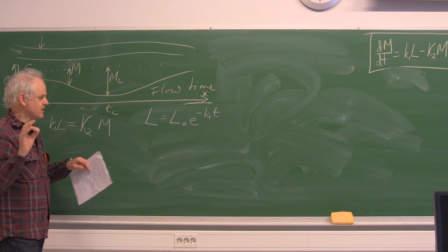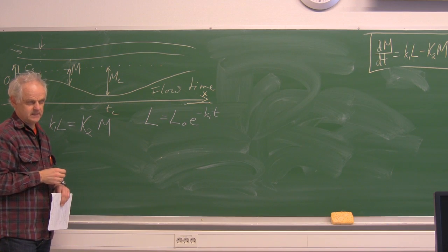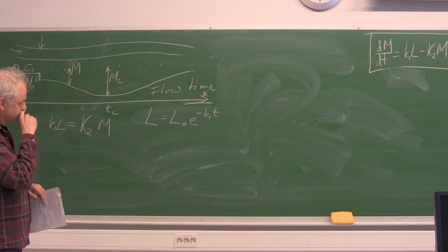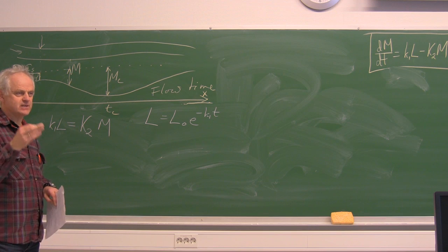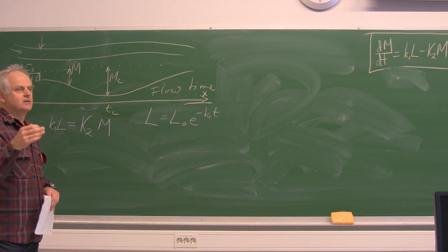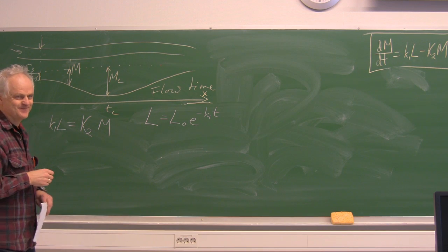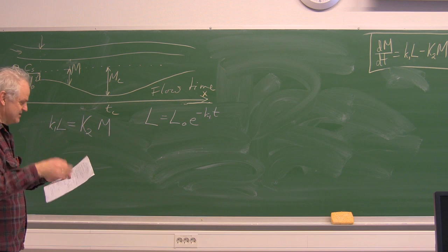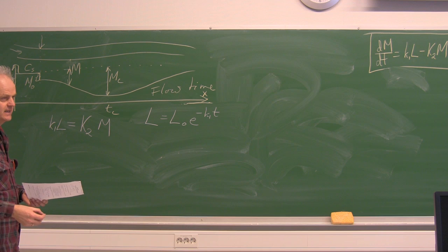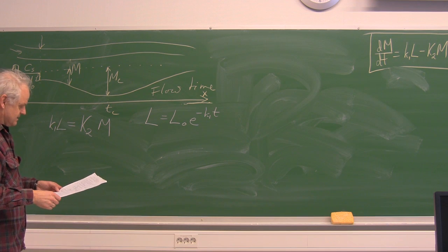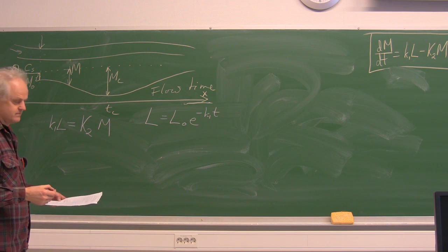So the modern BOD test is almost like a direct simulation of what happens in the river, except you have a constant KLA that is set by the apparatus. By the way, supposedly the reason the 5-day BOD is still standard is that the Thames River typically takes 5 days from the city to the sea. So some old ideas, history, can remain as the standard after 150 years. Many discharge limits are still given by BOD5 values.